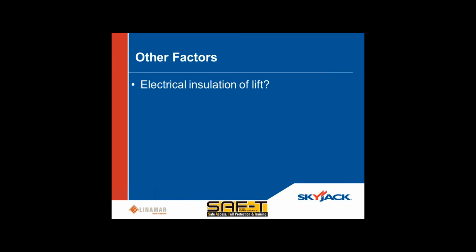So other factors that are potentially out there: electrical installation of the lift. Are you going to be working near power lines deliberately and understanding that? Do you need a lift that is electrically insulated in and of itself? Is there a confined area at elevation? Do you have to try and get into a very small area? Do you need a small basket or a small platform, or do you need a specialty machine to actually get into that area? Are you anticipating wind? Have you got an indoor or an outdoor use for this particular task to achieve?